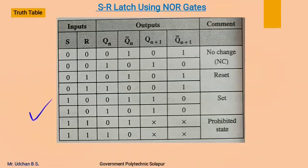So this is the summary of all the conditions which we have discussed earlier. This is our case 1, in which S is 0, R is 0. This Qn and Qn complement are the output state before applying the inputs, that is named as a present state.